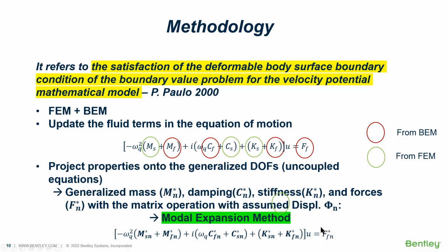Here, linear superposition of the displacement and the forces will be used for all the computations such as motion analysis or time domain simulation, etc. This is called hydroelastic analysis through the modal expansion method.